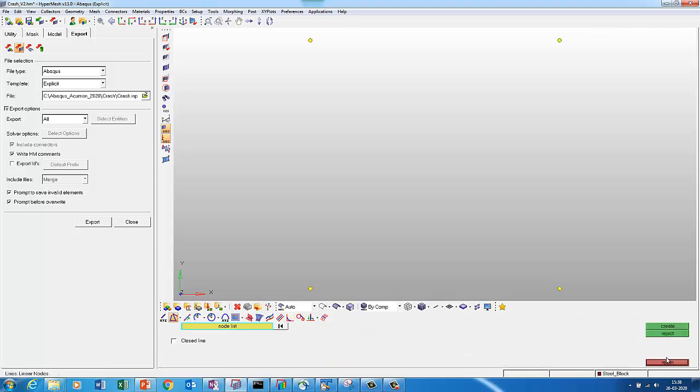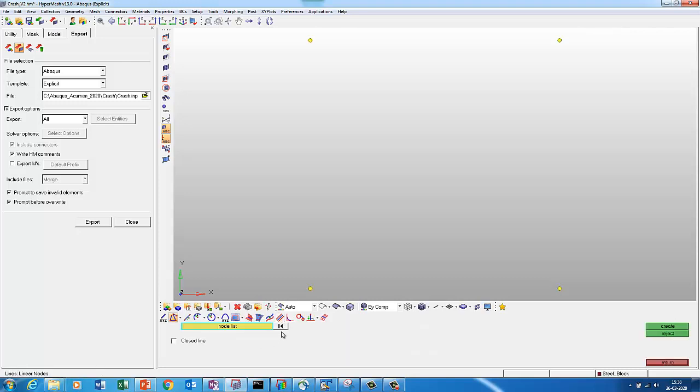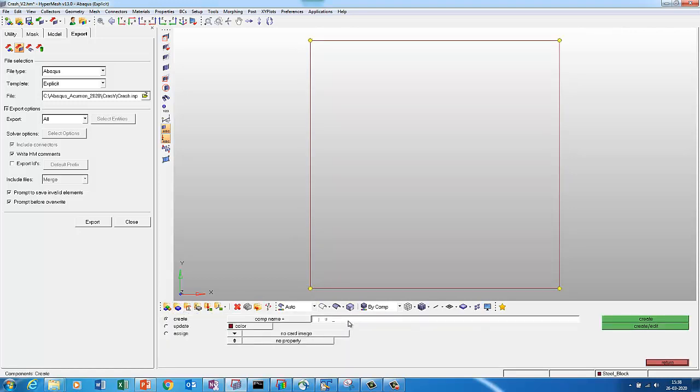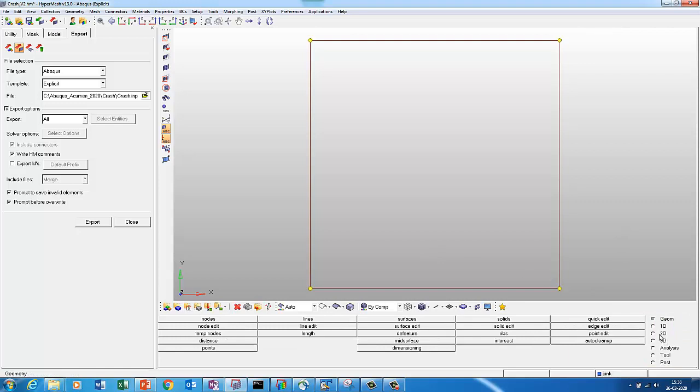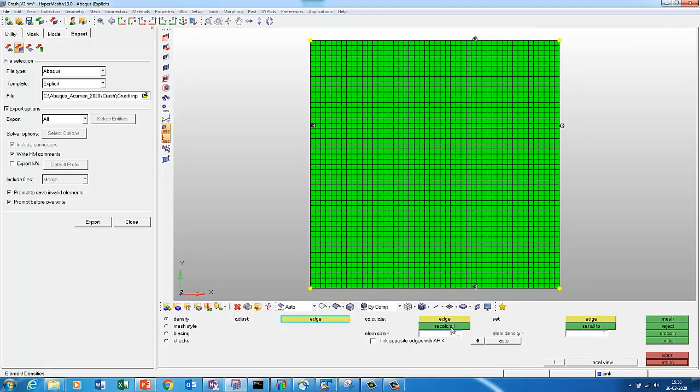I'll create a geometry, and I'll say create lines. I'm not interested in the stress level in the block, so block is just an impactor. So I'll create one more, something like a junk to have a shell here. So I'm going to put first shell, and I'm going to extrude the shell in one direction. So I say ruled, I select first line and second line I created, and I wanted something like a 5.